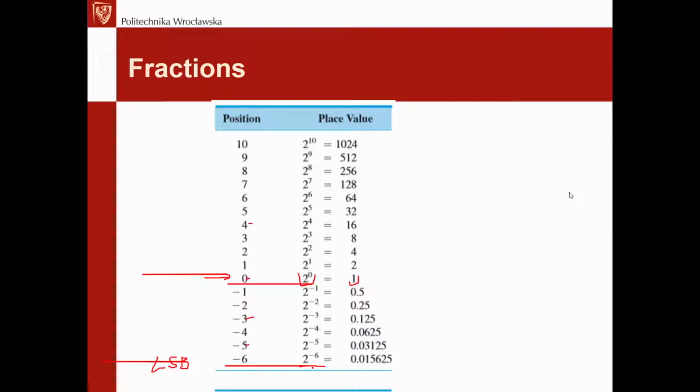And of course, if you start to share code, or compose your software with code developed by other persons, each one can use a different fixed point position, meaning that you may very easily get false results. So that's the disadvantage of this method of coding.